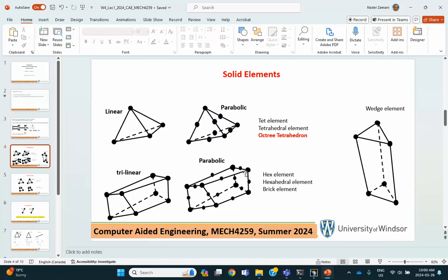Let's make sure that this actually is 20. I'm pretty sure it is, because, so let's see, now on this side you have 3 and 3 is 6 and 2 is 8. Yeah, 8 and 8 is 16, plus these 4 is 20 nodes. Okay, these kinds of elements, you cannot do in the generative structure analysis within CATIA.